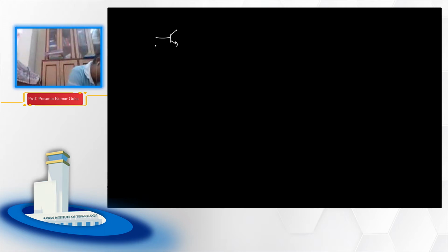When we look from the base side, of course the emitter is AC grounded, then we will see R pi. When we look from the collector side, this resistance is usually R naught if there is no RC there. If there is RC, then it will be R naught parallel RC. And when we look from the emitter side, without any early effect consideration, then this will be 1 by gm. So these are very important, and you will see we often will use them directly. So this part we have learned in the last class.